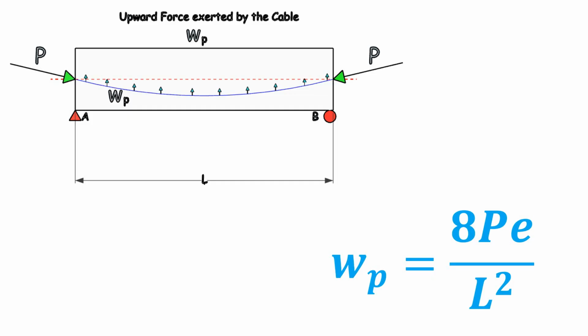When people go for precast pre-stressed beams, most of the time the profile is provided as parabolic, because this parabolic profile will have a good effect and enhanced upward force which is going to be provided by this cable, and it will be efficient for increasing the capacity of the beam when compared with the RC beam. This pre-stressed concrete beam has a higher capacity because of the parabolic profile. So this is a great advantage of the parabolic profile of the cable, which is being embedded inside the concrete beam